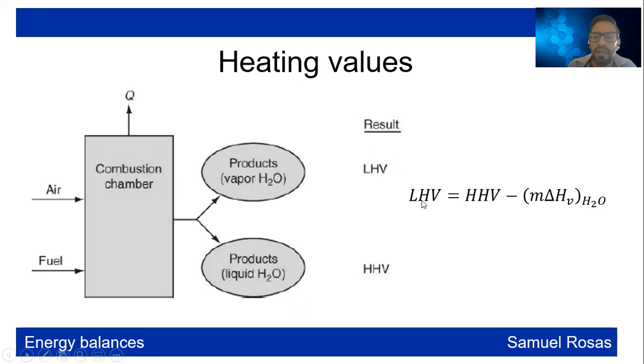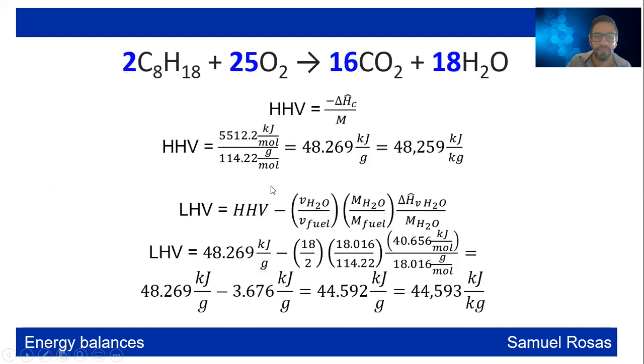So actually the low heating value is equal to the high heating value minus the enthalpy of vaporization of water times the mass, of course, of water, because you are just sending the liquid to vapor, okay? Here is an example of how to calculate these heating values.